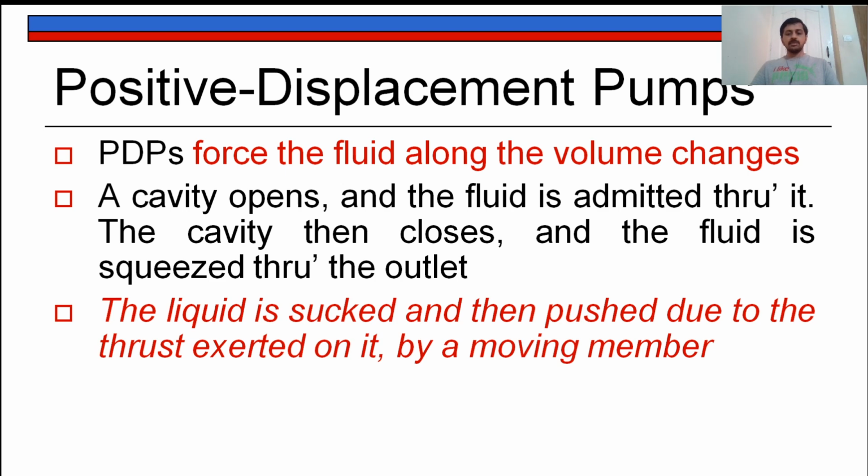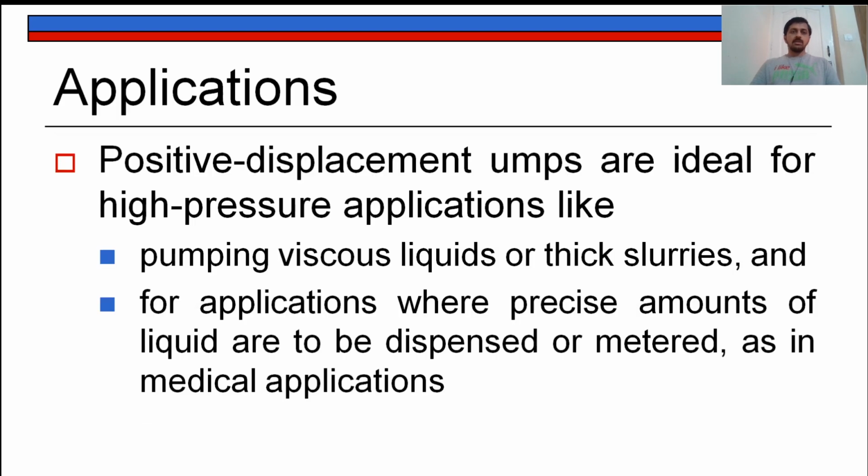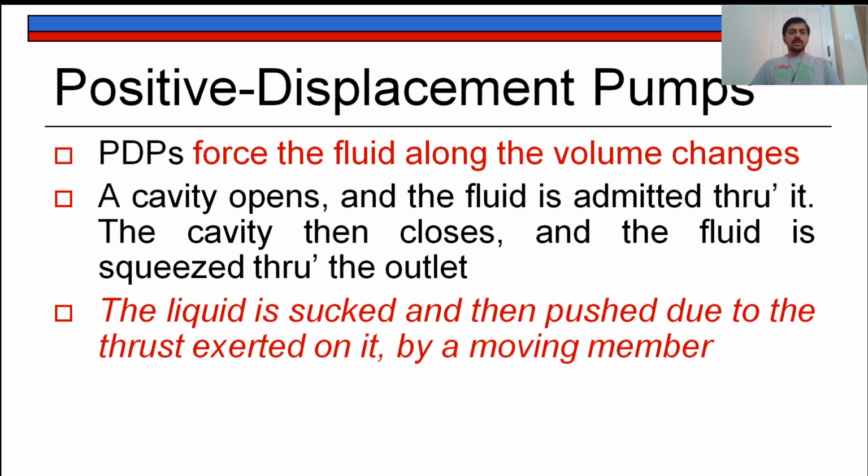Now, as we have mentioned, there are two categories of pump: positive displacement pump and rotodynamic pump. Now, positive displacement pump, as we have mentioned, will squeeze out a certain quantity of fluid from one place to another. Imagine a piston cylinder arrangement, or some gear kind of arrangement, or vane kind of arrangement. All these could displace a certain quantity of fluid from one place to another.